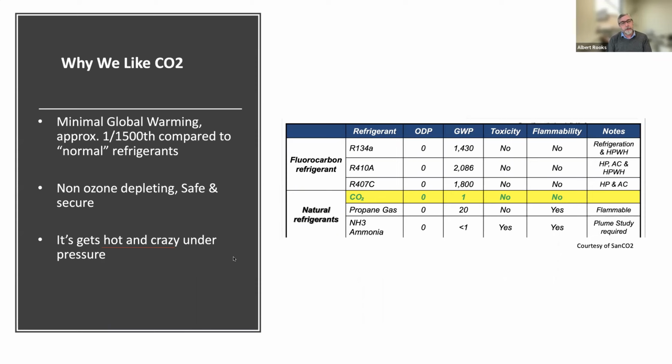But so far where we've come from is we have some fluorocarbon refrigerants. They have higher GWP, so that's a bit of a penalty for us. But also the 410A, 134, these refrigerants have a hard time working in colder ambience, and at the same time delivering a really high output temperature off the heat pump. CO2 has none of those issues.